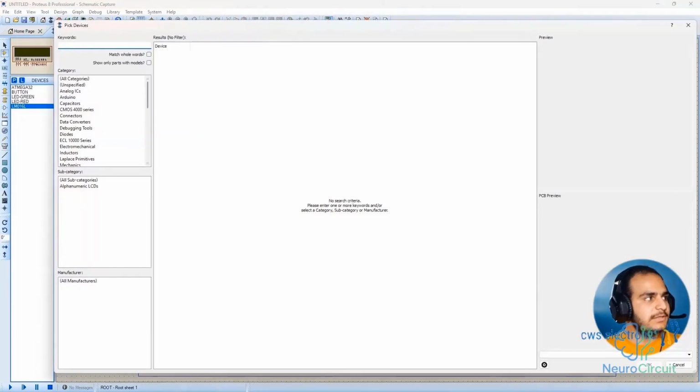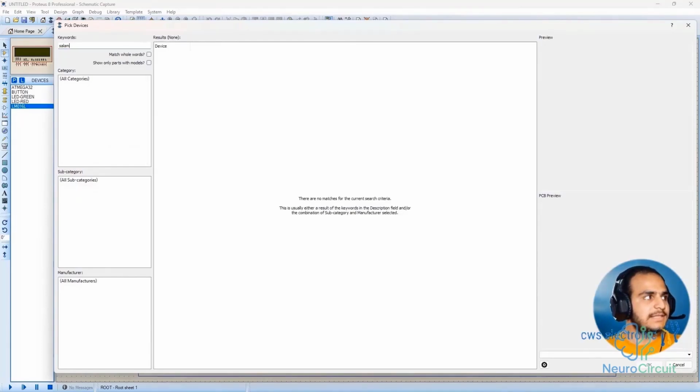But now, if I want to give you an example, for instance, if I want to write salam, how many characters is that? That's 5 characters, and the 16 by 2 LCD says, I have 2 lines, and on each line you can display 16 characters. Another point is that these LCDs only support English letters, numbers, and a few special symbols. And if you want to display Persian text, that falls under the topic of graphic LCDs and generally more advanced discussions. But for displaying English text, these character LCDs are actually one of the best options.